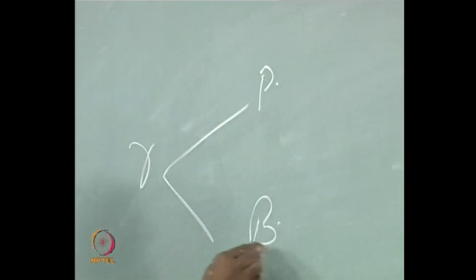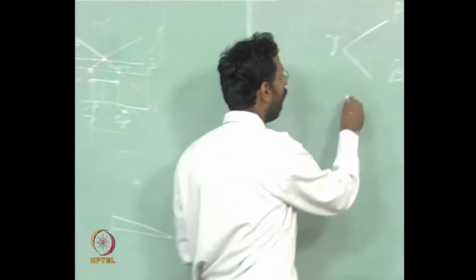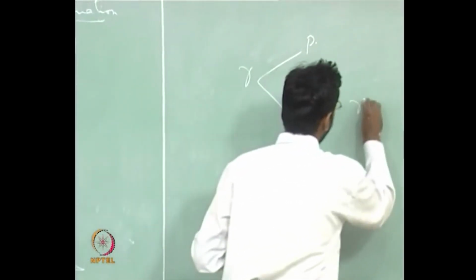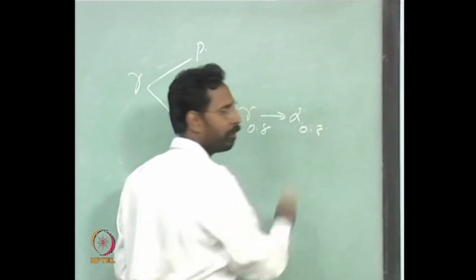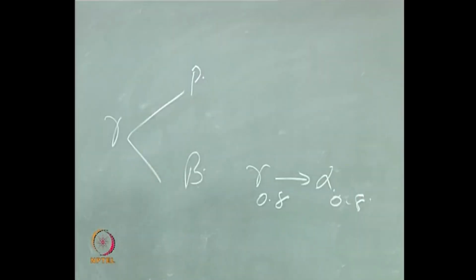In gamma giving bainite we have undercooled to such an extent that the carbon is not able to move much. Because carbon is not able to move much, long range diffusion is difficult, though short range it can possibly still do. As a result gamma first becomes alpha of the same composition, polymorphous.